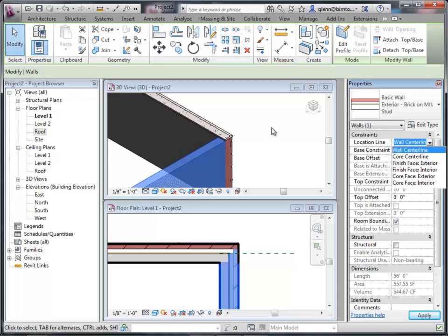I can draw that straight. On the outside, we'll often have the plywood lapping down all the way over all those things. We'll also have the finish layer, whether it's siding or shingles or whatever it is, coming out here. We'll have some sheetrock in here. It's a very typical wall assembly for around here. So, as you start thinking about how to place your walls, of all the different areas that you could use, there's the whole notion of the center line, which is very rarely used to place things.